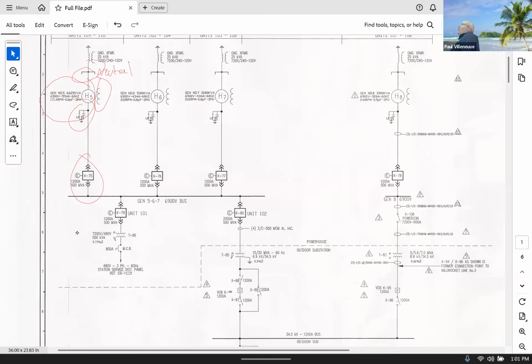And how much current should be flowing in your system under all the conditions we've talked about? Remember 3-phase systems when we looked at Y-connected systems? And if they're perfectly balanced, how much current is flowing? Because you have 3 wires that go into this common thing. We'll just show it as a ground for now. So I have 3 currents here. And this is IA, IB, and IC. What would those currents sum to? Because it's just a KCL, right? The sum of the currents into a node equal the sum of the currents out of the node. So the current going to ground or neutral is going to be equal to the sum of those currents.